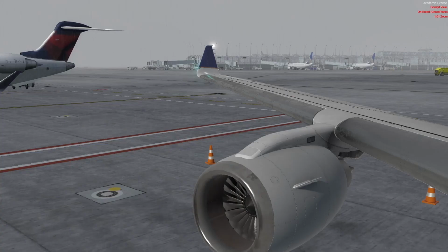The Embraer E170/190 family anti-ice system, or as it's usually called, ice and rain protection system, goes beyond just the engines and the wings. It includes things like heating for flight instruments, smart probes, windshields, water pipes within the aircraft, etc. Today, however, I only want to focus on those components that use the bleed air system to heat the elements. Those items are, of course, the engine and wing anti-ice system.